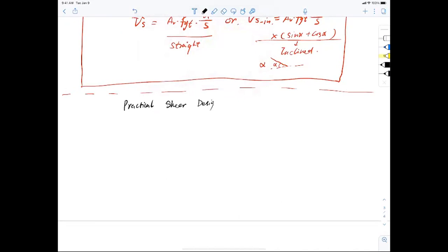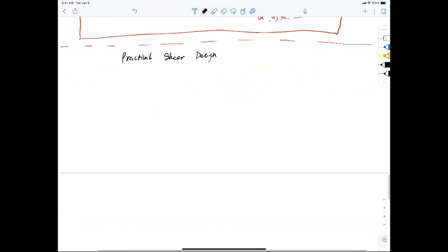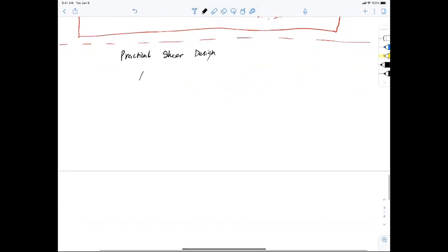If you look at the table 22.5.1.1, we said there's a term called Av,min. So what do I mean by that? Why is there a term called Av,min? Av is what? The area of the stirrups for shear, isn't it? And how do we determine Av? We don't determine that. We actually determine spacing. Is that right? But apparently there are requirements from ACI that say you have to put some stirrups in. Now I understand that, right? I need to have stirrups.